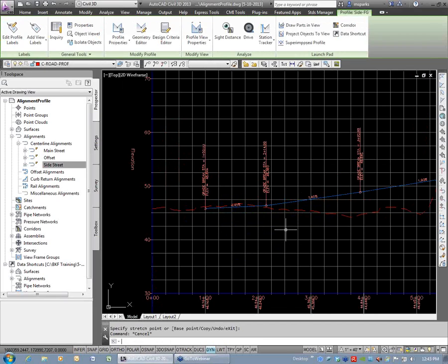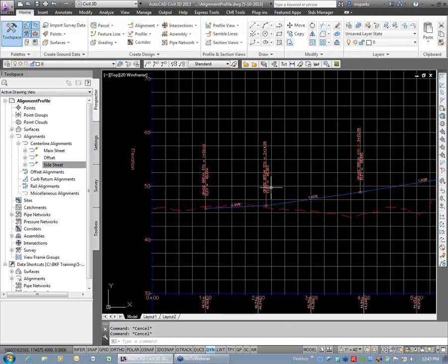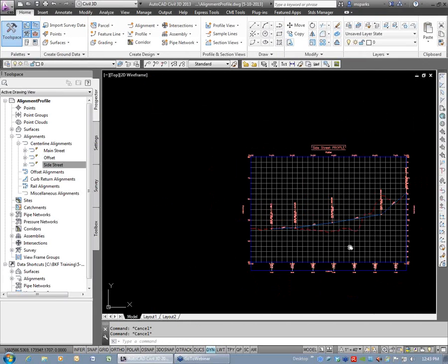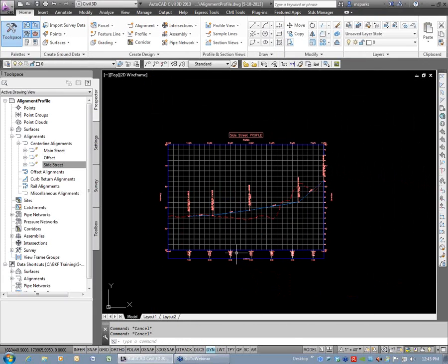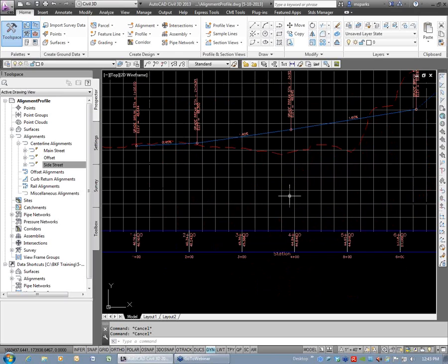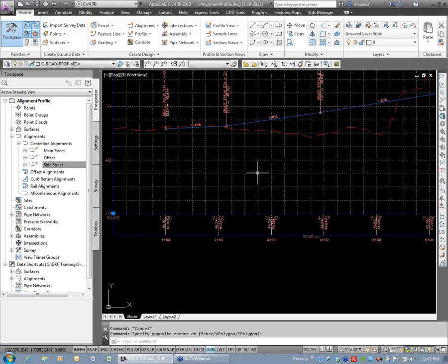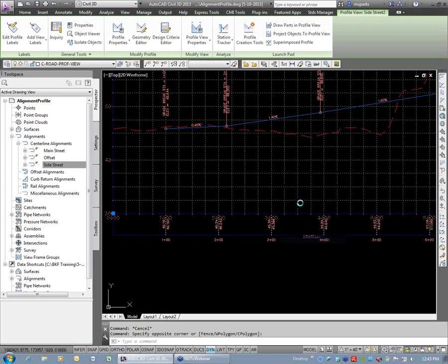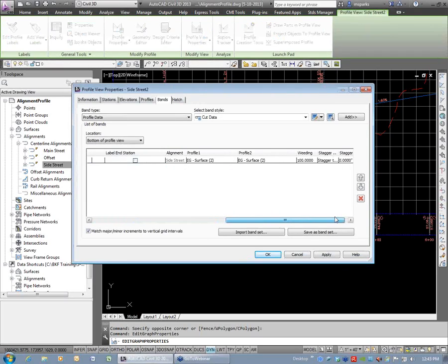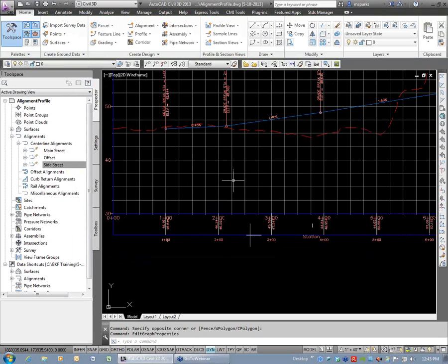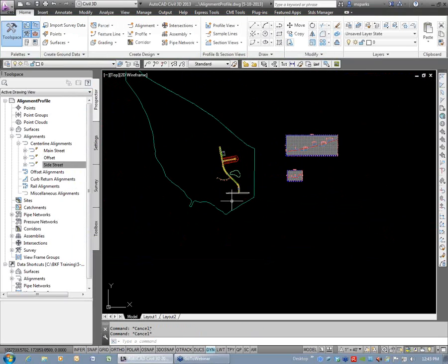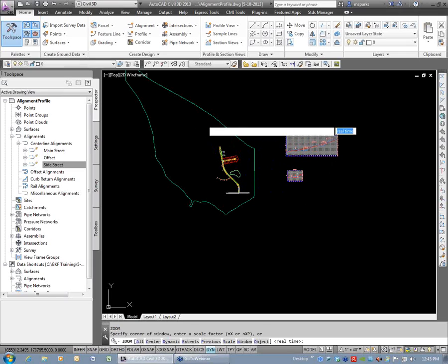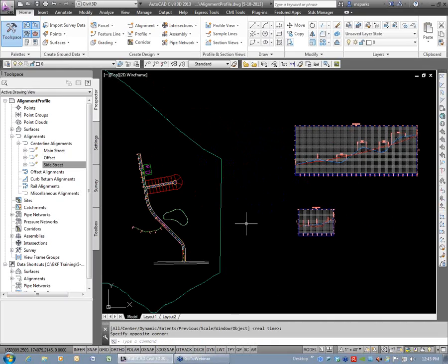All right, I'm going to move this over here just to be different. We wouldn't have had that problem if this is the case because they're outside of 100 feet now. All right, I can do profile grades, etc., or vertical curves, I could do that also. And the last thing is to go to my profile view properties and change my profile 2 to the side FG so the numbers are right. So you can see here a lot of setup to get the alignments, the profiles, and the design done here. Okay. Turn off my DYN, good old Q save.